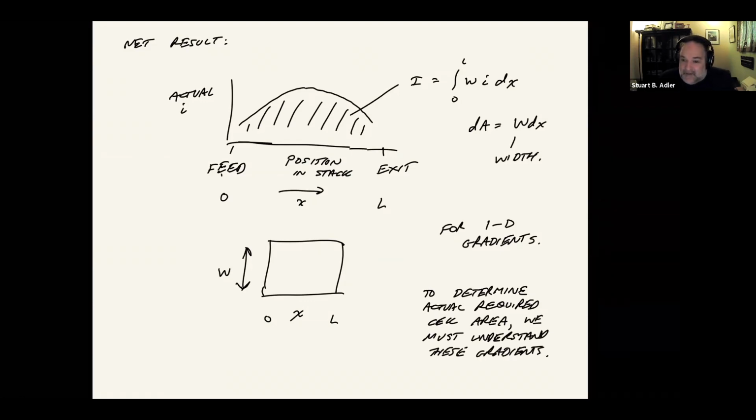And it can be impacted a lot by choices that you make. So I just talked about cross flow versus co-flow. Other things are like, do you make the interconnects out of metal that is highly thermally conductive or not? That's another issue. If the only things carrying heat are the gases, that tends to make temperature gradients worse because gases come in and they heat up as they go across the stack and they go out hot. And there's no way for thermal energy that's generated at the tail end of the stack to flow back to the beginning of the stack because the gases are going this way.